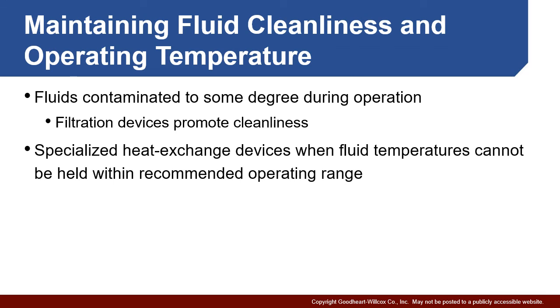Lastly, I want to reiterate that fluid cleanliness and maintaining proper operating temperature are essential to the overall function of your hydraulic system and can't be overemphasized. Fact is, regardless of how careful we're about it, some level of contamination is going to get into your fluids, so a filtration device is going to be necessary, and maintaining that filtration device or filtration system is essential for the overall cleanliness of your material and the long-term functionality of your hydraulic equipment.